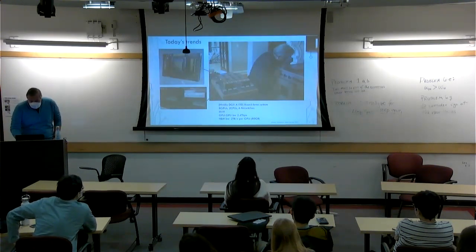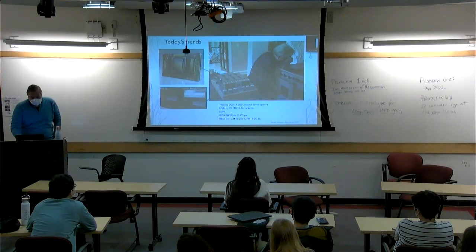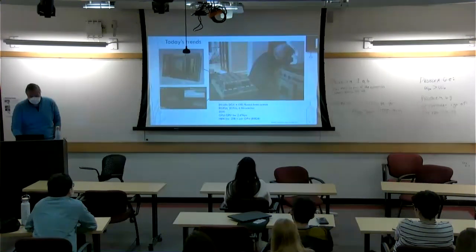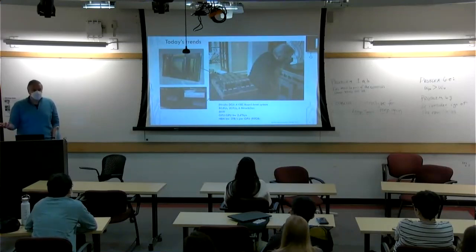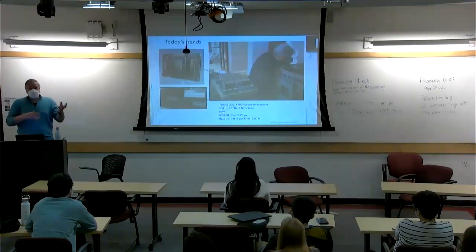So what you see here is basically the GPU here with 6 HBM chiplets, and the big cooling fans or heat spreaders are for the 8 GPUs, and then you'll see 6 switches. These are switch ASICs, NVSwitches, that create basically 6 different planes over which every GPU can talk to all of the other GPUs, right?